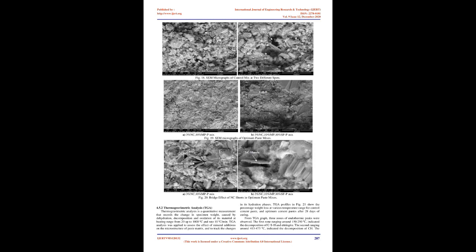This can be comprehended from Fig 18 by the presence of ettringite needles, calcium hydroxide crystals, CH, and voids leading to a loose structure. In addition, discontinued calcium silicate hydrate CSH plates were also identified. The optimum presence of hybrid NC and MP in the cement paste matrix, either SF was added or not, improved the consistency and the homogeneity of the matrix, leading to more compact structure, see Fig 19. The enhanced mechanical properties of the optimum mixture were confirmed by SEM micrographs.